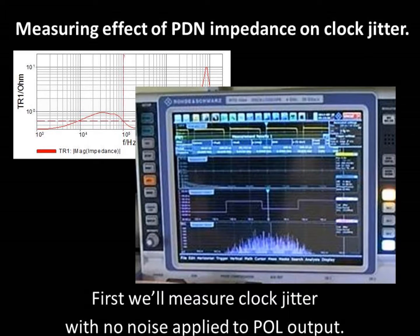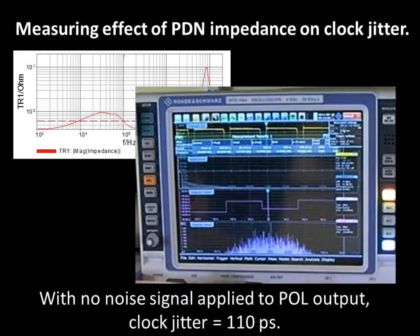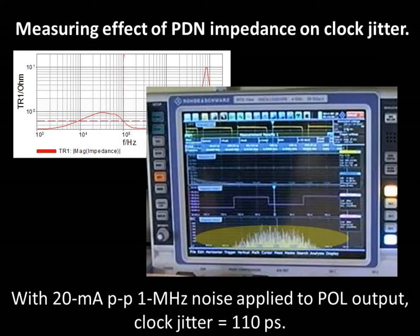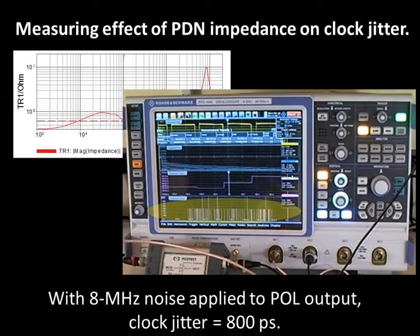But first, we'll measure the clock jitter with no noise modulation on the power supply. In this case, we measure the clock jitter to be 110 picoseconds. Now if we modulate the power supply with a 20 milliamp peak-to-peak sine wave at 1 MHz, we see that our measurement of clock jitter does not change noticeably. However, if we increase the frequency of the signal modulating the power supply to 8 MHz, we see a very sharp rise in the clock jitter up to a value of 800 picoseconds.